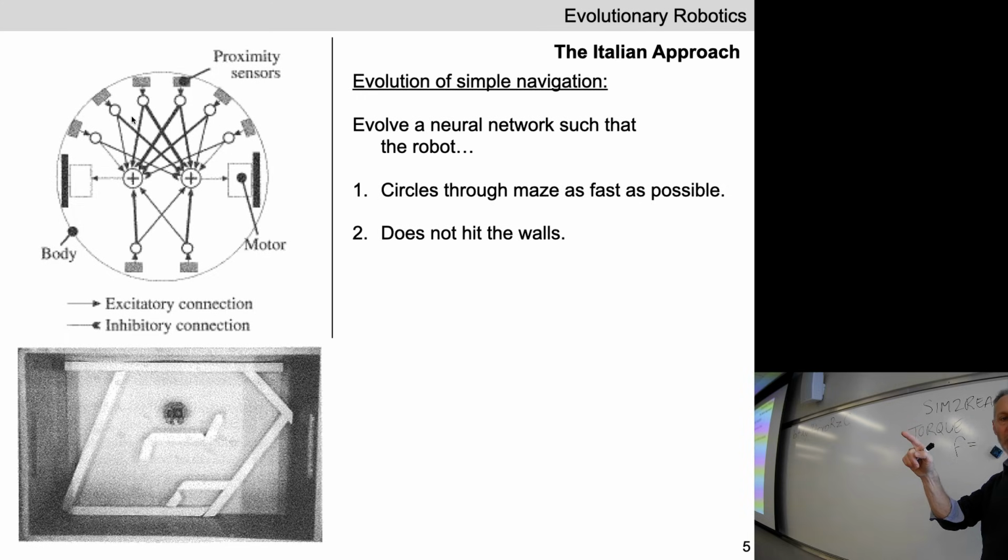As you pointed out, if you look at, for example, the three front left proximity sensors, the contralateral connections, the ones that cross the side of the robot, those arrive as inhibitory connections. So contralateral inhibitory connections do what? If we have more proximity over here, they more inhibit this wheel. More proximity to the front left slows the right wheel, which causes the robot to do what? Turn away from an oncoming. Turn away.